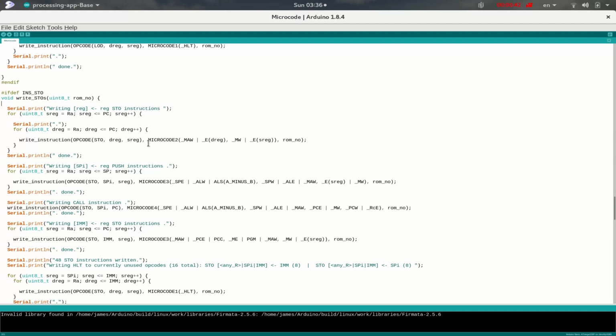And the microcode for such an instruction contains 2 steps, as we saw. And so in the first step, we want to enable this destination register address, which we will then write into the memory address register, so we can point the RAM at the address to which we want to write the data in the source register. And then in the second step, which corresponds to time t3, we will enable this source register, the value, straight out onto the bus, and then simply write it using this memory write signal.